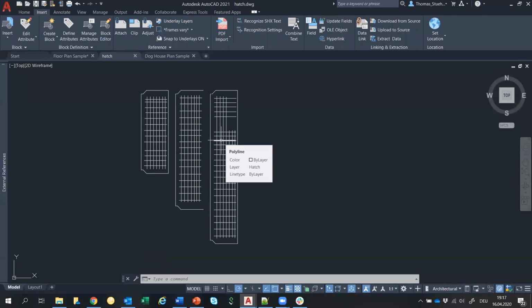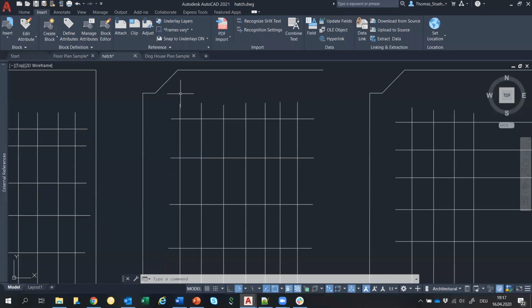Now, the intention with the enhancement is to make the workflows for the commands quicker and to speed up productivity. Now, within previous versions, whether the requirement was to make all entities either cutting or boundary edge, keys like return, enter, or spacebar had to be pressed, or the right mouse button had to be clicked on the first prompt. And this is no longer the case.